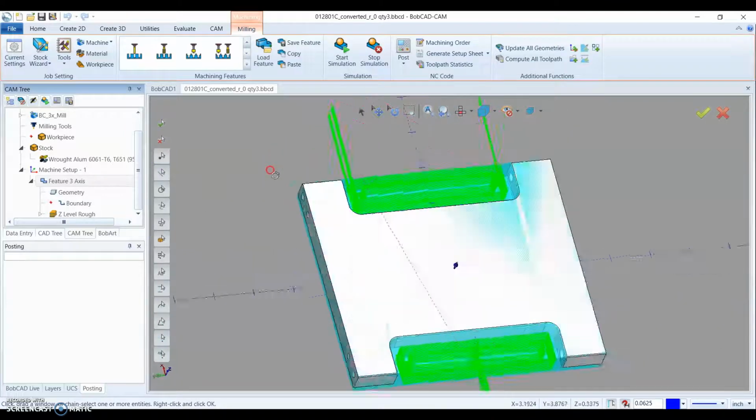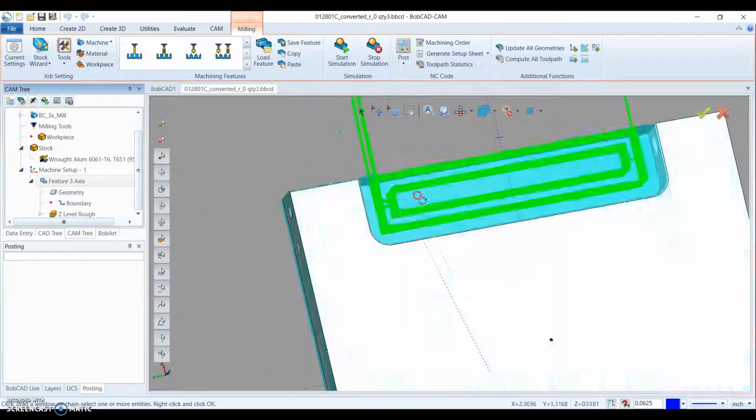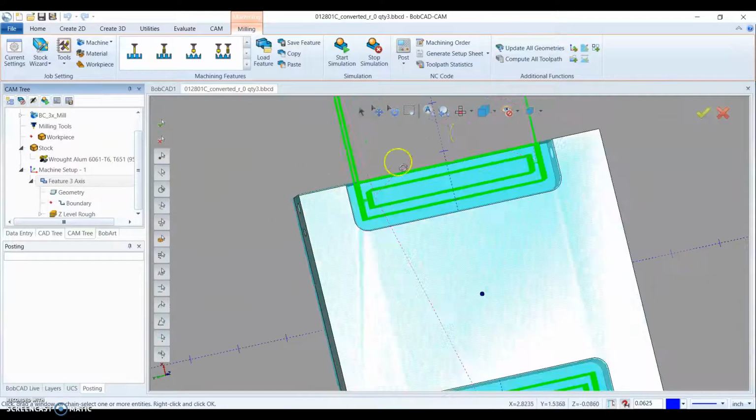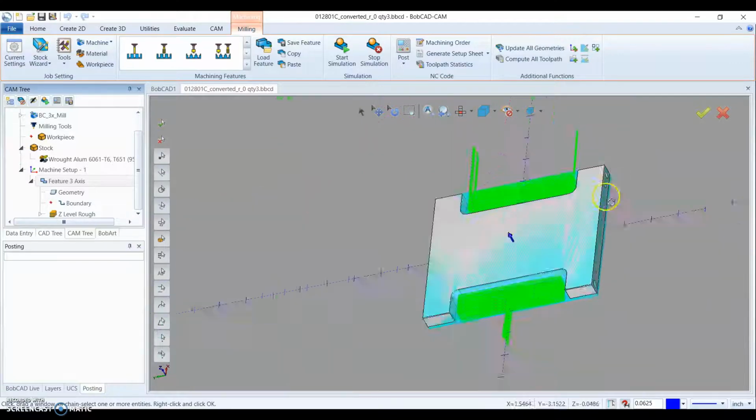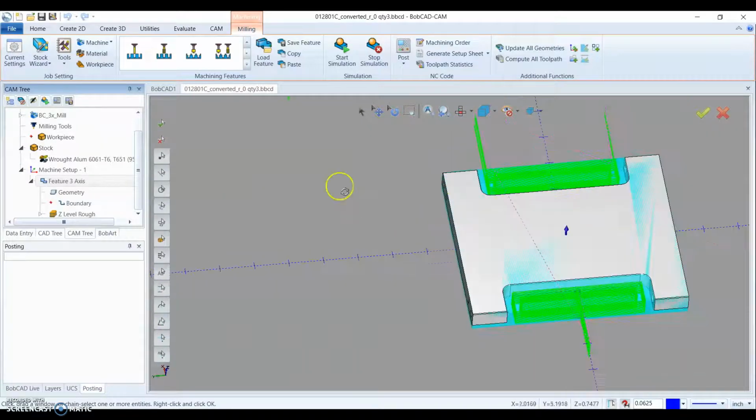and you'll see, so at that 3 inch lead in, well, that's kind of overkill, right? But also it didn't machine the outside of this like I want it to, right? Well, why didn't it do that? Well, it didn't do it because there's no extra stock outside those. So in order to get it to do it, I just right click here.